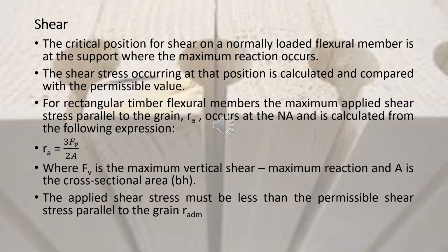Now, the critical position for shear on a normally loaded flexural member is at the support, where we witness maximum reactions. The shear stress occurring at that position is calculated and compared with the permissible value.